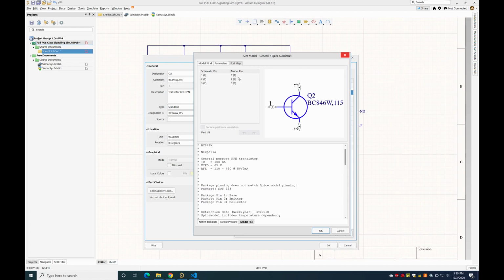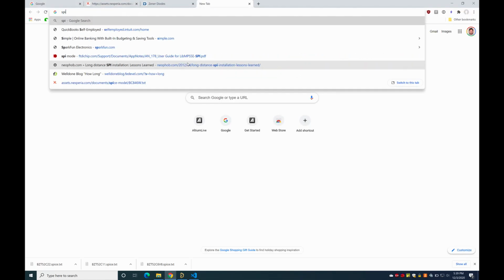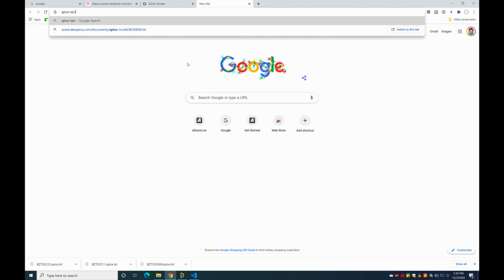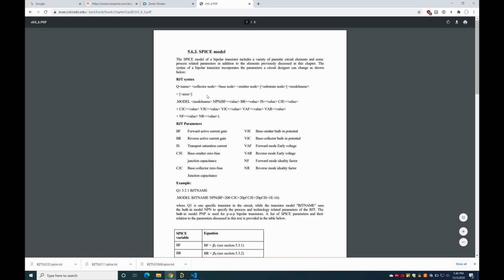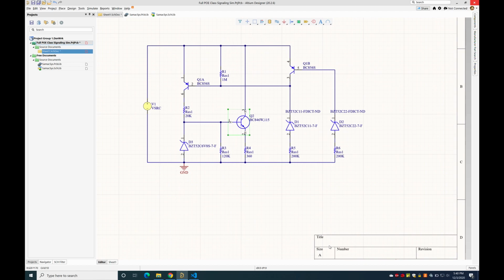So it turns out that in SPICE, a general convention is BJT pins go in order collector, base, emitter, pin 1, 2, 3, which is actually, we see, different for this model. So the pins aren't going to map up perfectly. Where SPICE assumes collector base emitter, this package is actually numbered emitter base collector, so exact reverse order. 1, 2, 3 becomes 3, 2, 1. So we just need to align that properly in the port map.